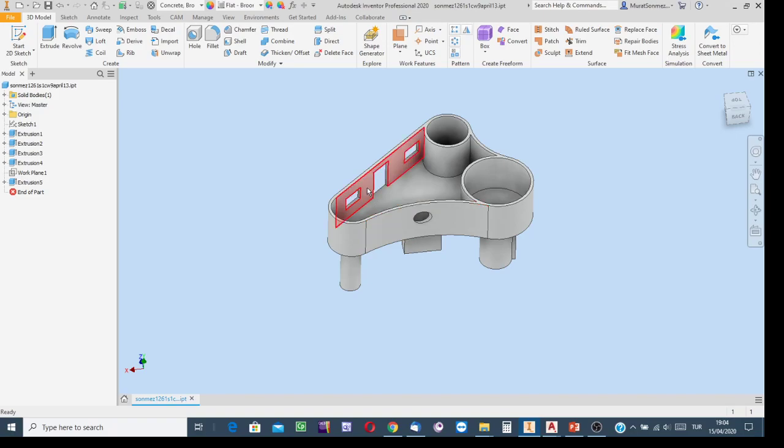Since I indicated this as the reference in the first demo for creating such an empty space, I drafted the sketch over the surface and applied the process, and the axis of the hole became perpendicular to the sketching plane.